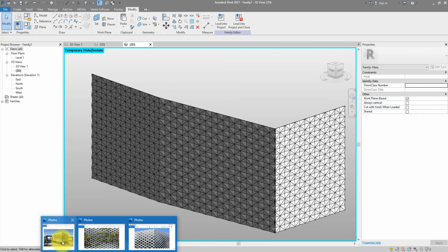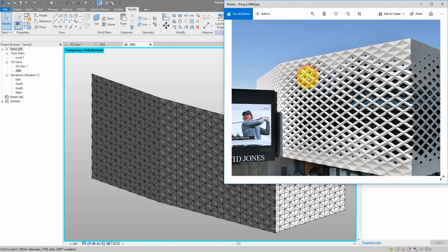But if you look back at the reference image, essentially we have only been able to recreate this part here, or at most a bit over here, because these are the only closed panels in the system. What about those? For those, you can either open up each panel individually or use Dynamo to do it quickly. Now, if you are new to Dynamo, don't panic, because this script is super easy and straightforward to create. And even if you have problems creating it, I will include a link in the description to download it anyway.